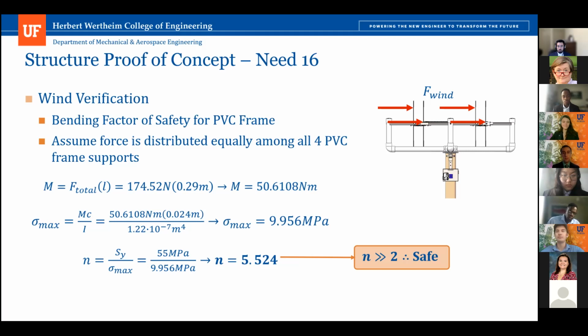I mean, it might be that at 60 degrees Celsius you start to have some long-term physical change to the atomic structure of the material or something like that. But 60 degrees Celsius is something like 180 degrees Fahrenheit. No, it's probably less than that, probably 150 degrees or so. But even at that temperature, metals will have some appreciable knockdown in strength. Maybe it's 5% for aluminum at 150 to 180 degrees. I would expect PVC to see something probably bigger than metal. So I'd encourage you to take a look at that.